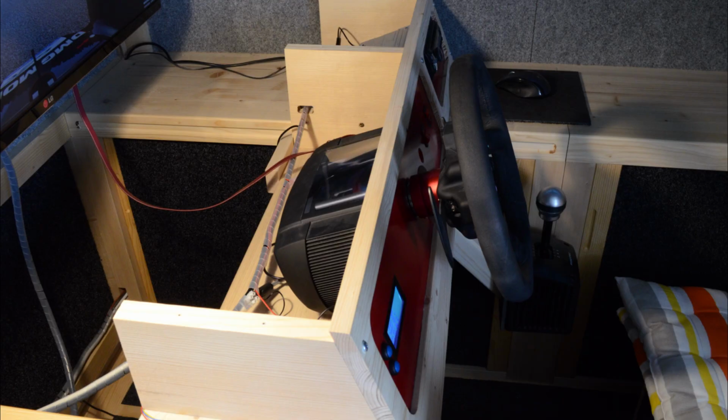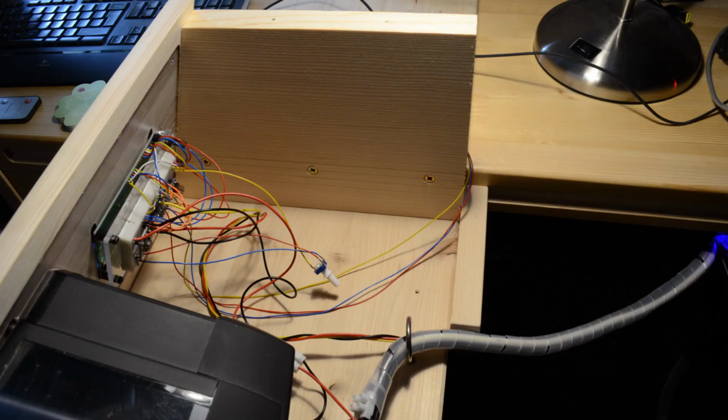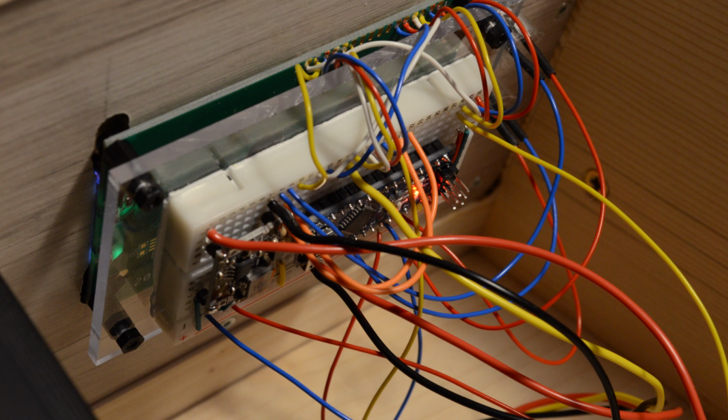So I've got the Arduino Nano mounted on the back of the LCD screen. As you can see here, there's a piece of plexiglass that is mounted on the back of the LCD screen with some nylon spacers, and then I've got a small breadboard that came with the Arduino starter kit, part of it, that I've glued on the piece of plexiglass, and then I've got all my components mounted on there: the Arduino Nano, some resistors, and also the little 12 volt DC to 5 volt DC converter that feeds the 5 volts into the Arduino Nano.